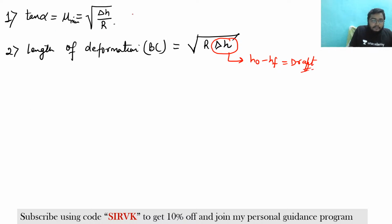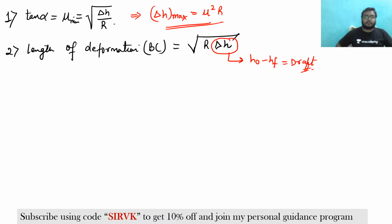From this only you can find another formula, that is delta h maximum is equal to mu square r. So the maximum possible reduction, that is the maximum draft, is mu square r. Now if you can remember these things, definitely you can solve each and every problem.